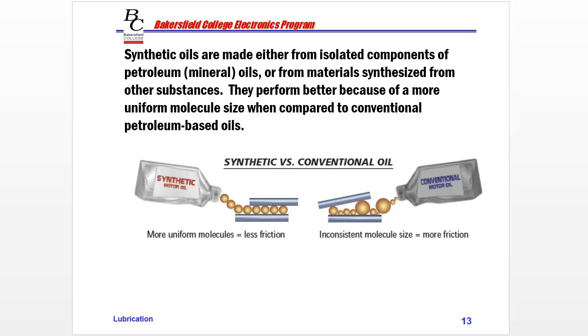Now, there's been a lot of studies done, and for the most part, whether you use synthetic or conventional oil in an automobile, they are fully compatible with each other. If we had a 5-weight 30 conventional oil in, and we were running a quart low on oil, and all we had lying around or in the store was a 5-weight 30 synthetic, we could simply add it to the conventional oil. We can mix these two. Now, we wouldn't want to mix it in an oil change, but we could.